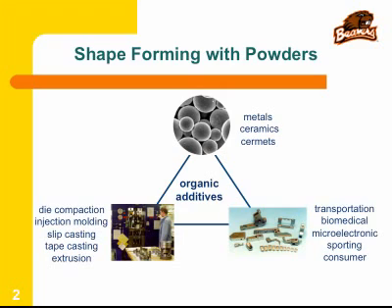I mean, take your zirconia particles, for instance. Right? You need them to be de-agglomerated. That is, the agglomerate should break down and it should disperse evenly. What might work for making a homogeneous suspension in water for zirconia might be different if for the same zirconia you use a different particle size, or with the same particle size you go from an aqueous medium to a polymer melt, right?